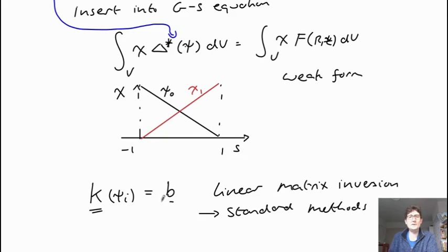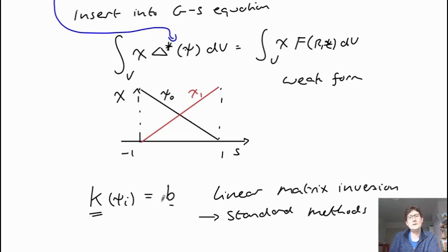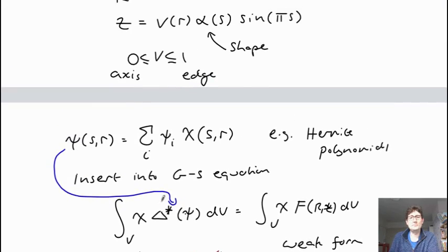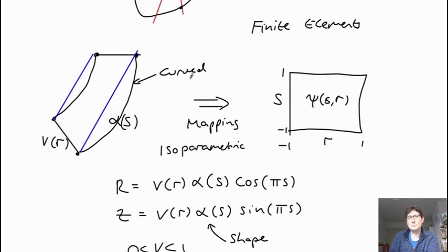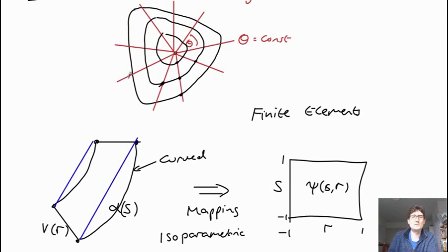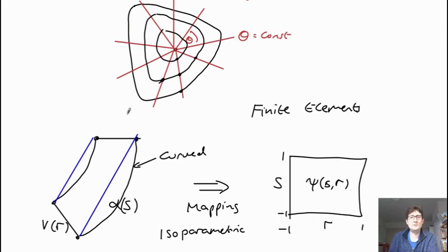So that's the basic idea of the finite element method used here. So you write in terms of basis functions. You put these basis functions into a standardized cell, and then use a mapping to map the standard cell into a curved cell. And the combination of these curved cells you make into a domain like this. And this method enables you to have very high accuracy solutions. So you get very good convergence and get very highly accurate solutions with relatively small number of cells.